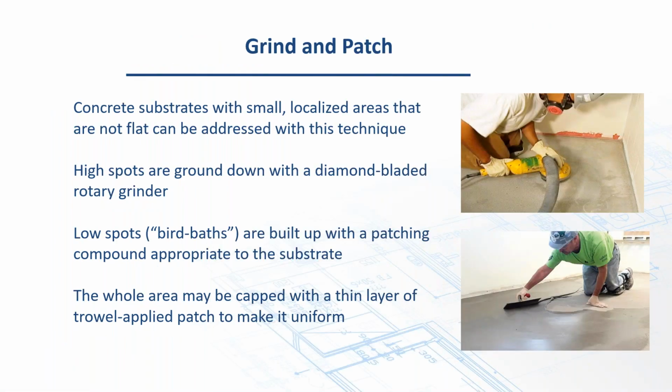Grind and patching. Like I said, this is commonly done. If the job's not real bad, if the concrete's in pretty good condition, quite often you can just grind down the high spots. Today, of course, you have to have HEPA filters and everything else to keep the silica sand down, but grind down the high spots, float out the rest of the bird baths, and get ready to start setting your tile. But take your straight edge, check all the areas, make sure you get it reasonably flat, otherwise you'll be fighting it the whole installation, guaranteed.